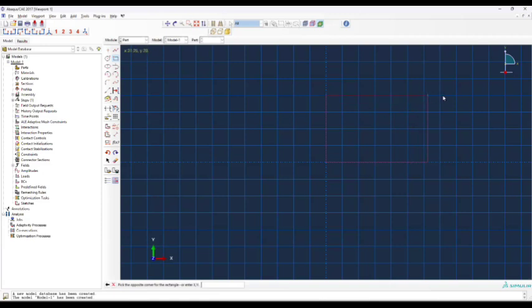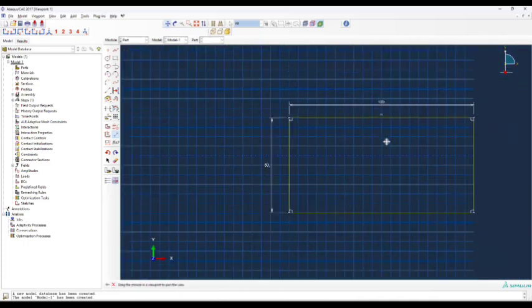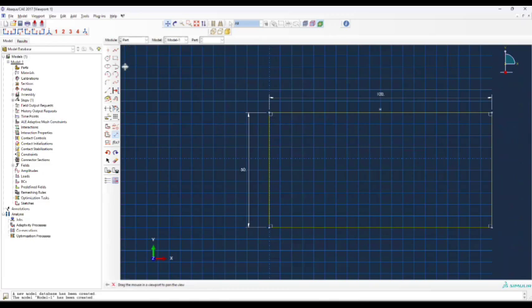So it's rectangular. I'm just going to start off with the dimensions. We said that its length was 100, and so 50 here and 100. Okay. Then this will go all the way across, and then we just need to assign this circle in the middle. So we've done the rectangle. Now I'm going to make a circle, center circle. You can put it wherever you want. I'm going to create the circle itself. And now through dimensions, we're going to position it right in the center, okay?